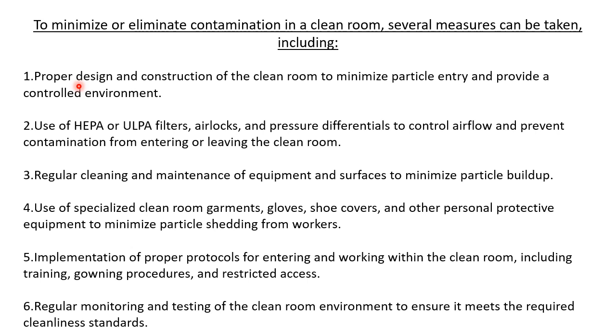Depending on the purpose, the designing of the clean room and the construction is to be done properly. When you do this, you will automatically minimize the particle entry and you will get a controlled environment. Then use HEPA filters, ULPA filters, air locks, pressure differentials to control the airflow and prevent contamination from entering or leaving the clean room. Then regular cleaning and maintenance of equipment and surfaces to minimize the particle buildup.